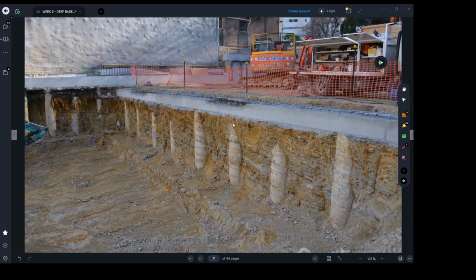Now, definitely at this stage, I can see the piles already built. This is what we call the pile cap. So on day one, what we do is excavate for the holes, whether it's going to be by drilling only or by CFA. This is up to the conditions. If it's very strong soil, which was agreed by the soil report, we just excavate.